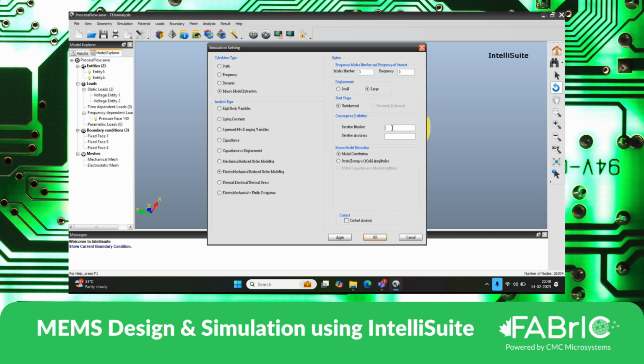And the iteration number should be minimum 100 and accuracy is 0.001, or if you want further accuracy, you can always add to this. And how many modes of vibration? So 3 modes by default. You can also reduce it to 2 if you wish to, but 3 modes of vibration is quite obvious. Okay, and typically the mode 1 vibration is always our fundamental mode.